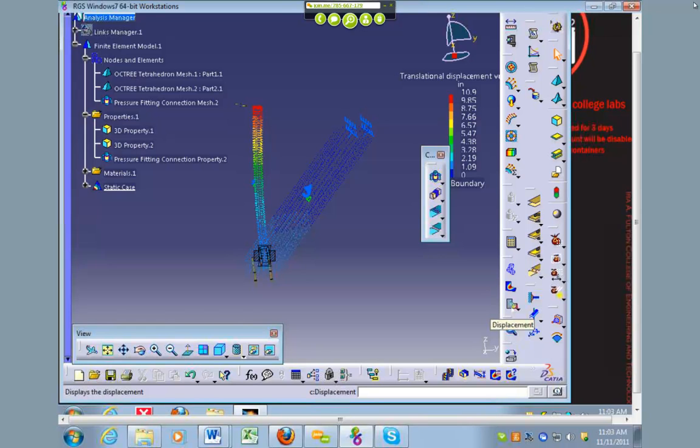Yeah, so I did 10,000 down on the beam, which is steel, and then it was negative 10,000 in Z, and then at the top of the beam, or top of the shaft, I put positive 10,000 in the Y direction. Right. So as you put that on there, you can check the displacements. You'll see there's a lot of displacement at the top of the beam, which is what we expect. There's a little bit more displacement down here.